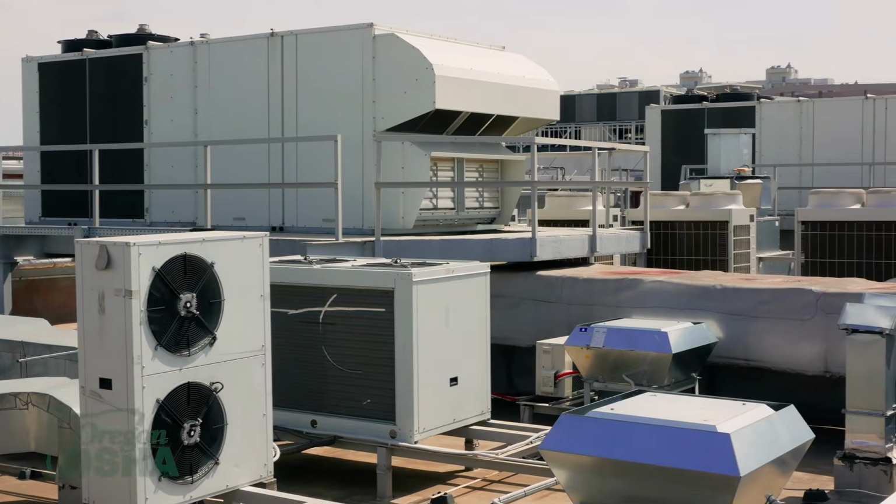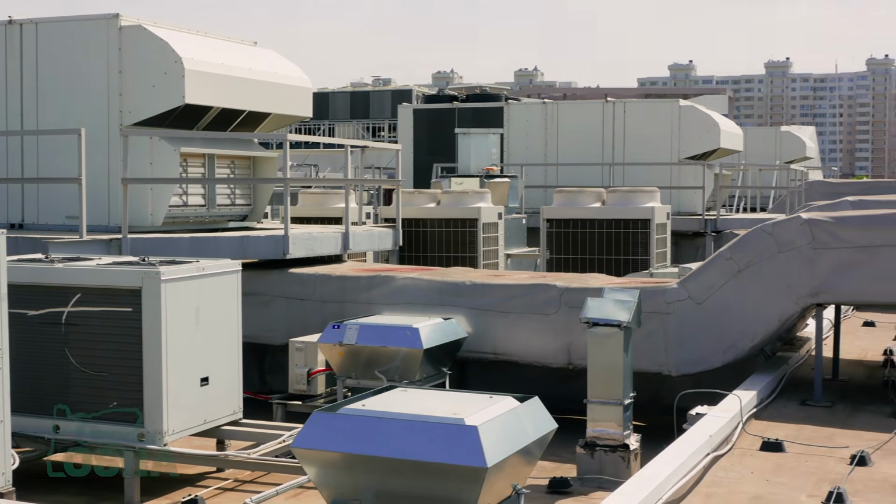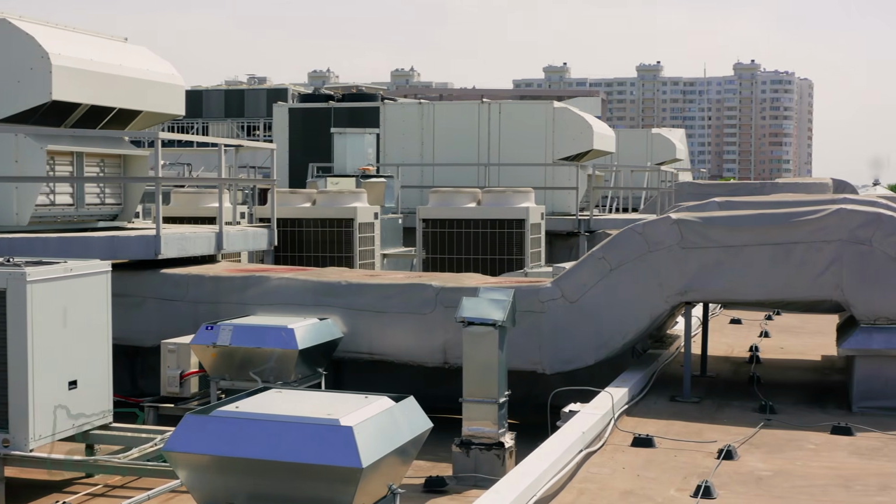We see guardrails set up in a lot of different industries. We see them on low-slope roofs, on commercial roofs, to keep people protected when they're working around either skylights or around the mechanical utilities that are on top of the roof, or having to do maintenance out near the edge of the roof where they want to protect a worker, but they don't want to have them in an active fall arrest system.